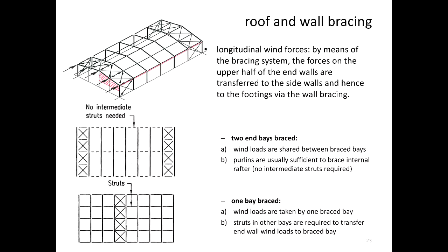So when you're building these structures, if you have a roof brace or a wind brace at the roof level, you must have a wall brace within the same bay as well, if that makes sense. Like this here, see, that one is brace, brace, brace. You definitely need to have that so that the load is taken to the ground.